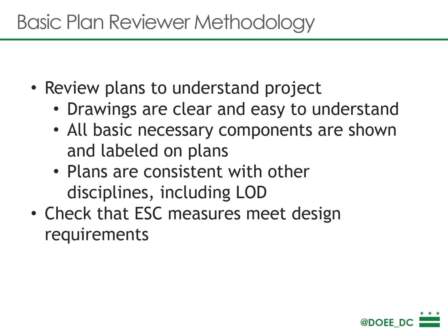A plan reviewer will typically first go through a project and review the plans to be sure they understand the overall project. The drawings should be clear and easy to understand, and all required pieces should be included. The reviewer will then go through and check the ESC measures and make sure that they meet design requirements.